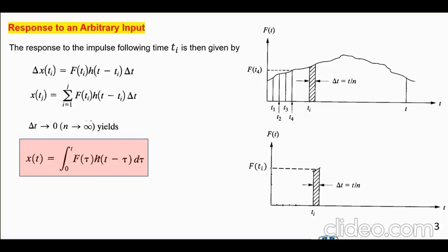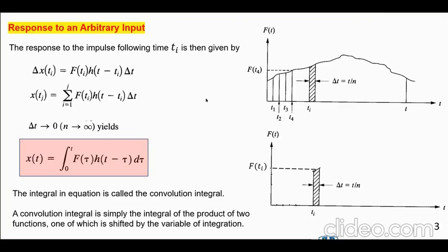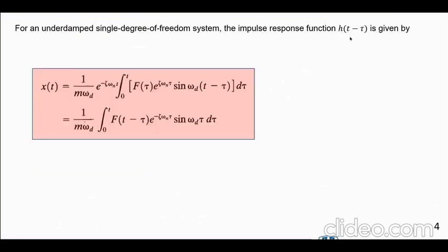And look, we have the impulse response function in it, and that's what I promised you on Thursday. This impulse response is going to come up for an arbitrary distribution of the function f. Okay, so that's exactly what I just said in writing. Now we go here. So if you have an underdamped single degree of freedom system, we actually found out what h was. Remember, we actually had an expression for it. And that expression, please go ahead and look at it.